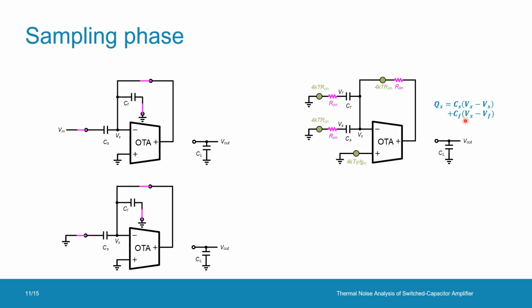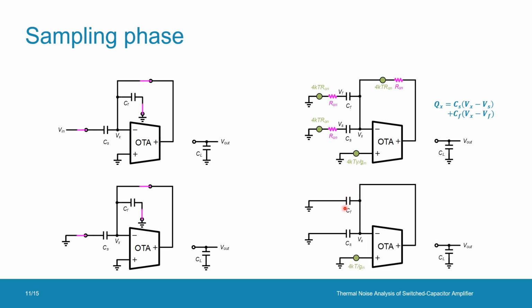Now, this calculation is going to be very tedious and probably pretty messy, because here we have multiple poles and zeros. So, in order to make this world a better place to live in, I'm going to simply ignore all the resistors and their noise contributions. Then you will find life is very beautiful, because now this complex network becomes a single pole system, like a simple RC low-pass filter.